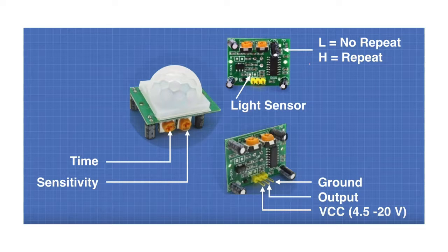But otherwise, if it does not repeat, it will only switch on and wait for the time it is told. Maybe switch on for 5 seconds. So after 5 seconds, the light will go off. You can find yourself inside the bathroom, using the bathroom, but the lights have gone off. It's not that there is power fluctuation or whatever. It's the sensor that switched off the power because it was probably set to no repeat, while you needed a repeat.